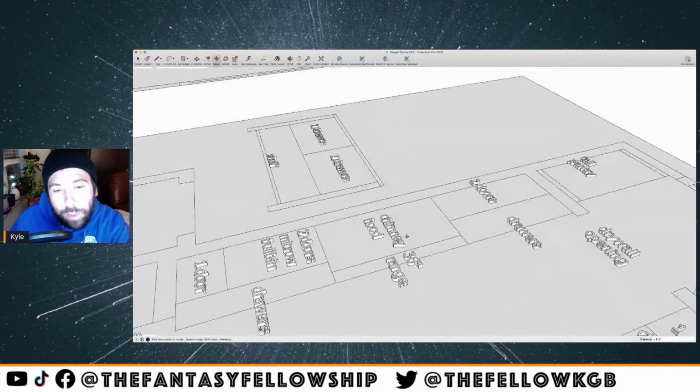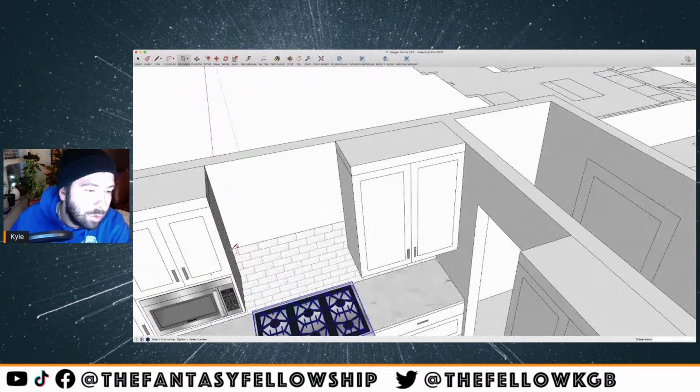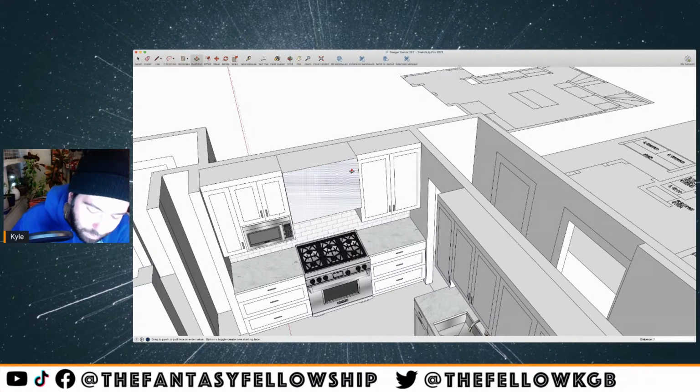And then she called for a chimney hood. That's going to be a stainless metal hood here. And I like to draw mine on my own. So I'm just going to make it square where I have the opening. I'm gonna pull this out. The cabinets are 16 inches deep. I'm gonna make my range hood about 20 inches deep. So I'll come out another 4 inches or so.